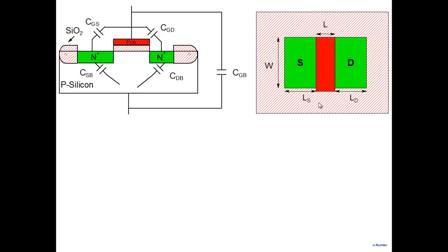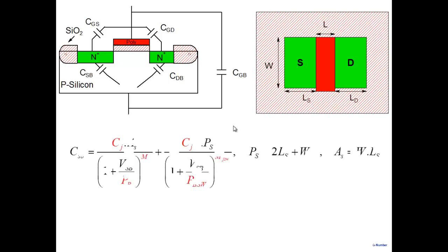Why do I cover with oxide? We'll see later on. So we have one transistor here, surrounded by oxide, to isolate one transistor from the other. Okay, so all around is silicon dioxide. So note that when I talk about capacitance here, the capacitance would have two components. I'm talking about source to body capacitance. It has two components. It's a PN junction capacitance, but with two components. One depends on the area of this region here,